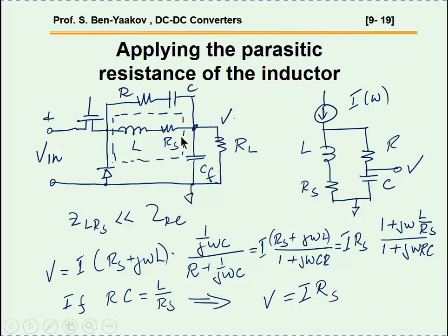To explain this, let me just go to this equivalent circuit. This is the current which is passing through the inductor, and I'm sort of bringing it into sinusoidal waveform. This is like Fourier transform, you might say. This is the path of the inductor, and this is the path of this filter. Here it is. This is this filter. Now the impedance of this path is much, much lower than this, so the current actually goes through here. Very little current goes in here.